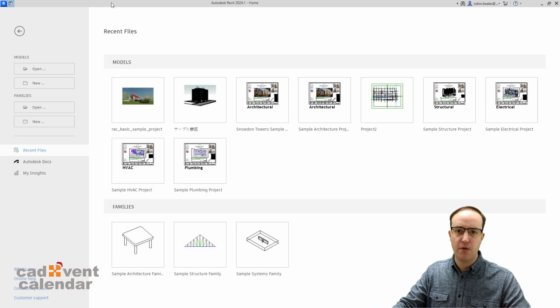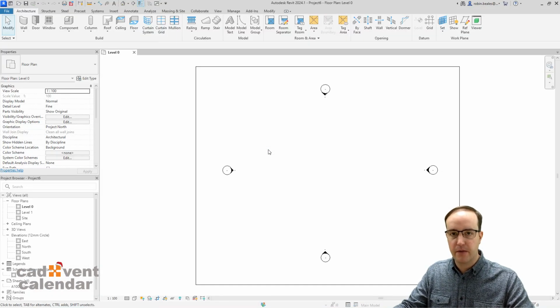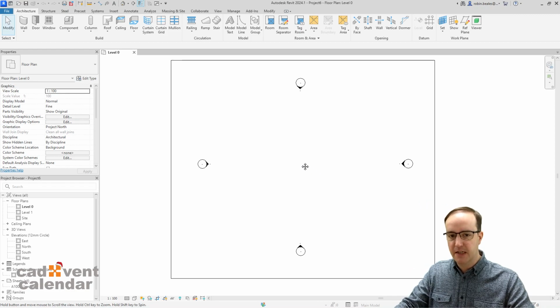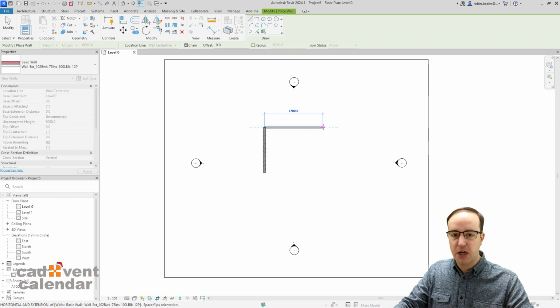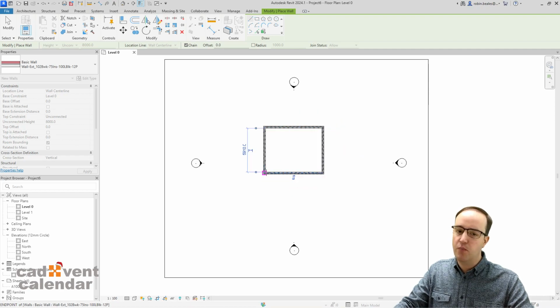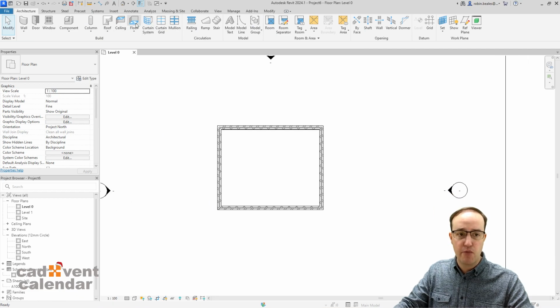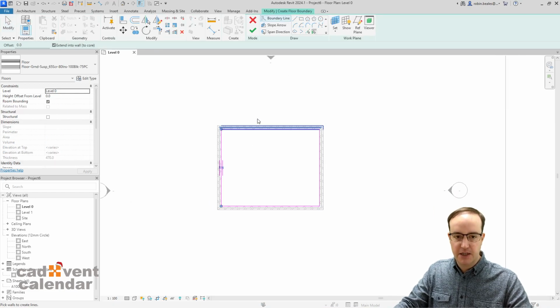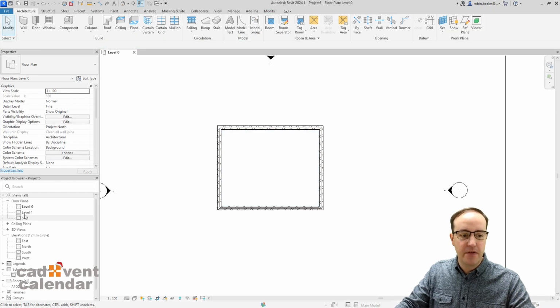And actually I want to go through the differences between them in Revit, because in Revit we do have two very different components, a room component and a space component. Typically speaking, if we're working in the realms of architecture, we work with rooms inside of Revit. A room is controlled by room bounding elements, such as walls and floors and ceilings and roofs.